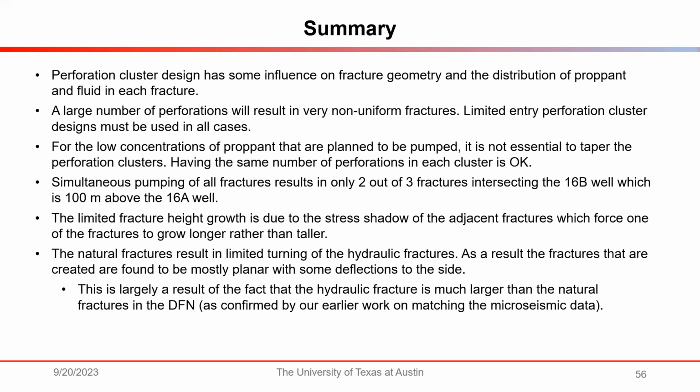So limited entry perforation designs are absolutely a must in most of these cases. So having a large delta P in the perforations is essential. For the low concentrations of proppant that are planned to be pumped, it is not essential to taper the perforation clusters. Having the same number of perforations in each cluster is okay.